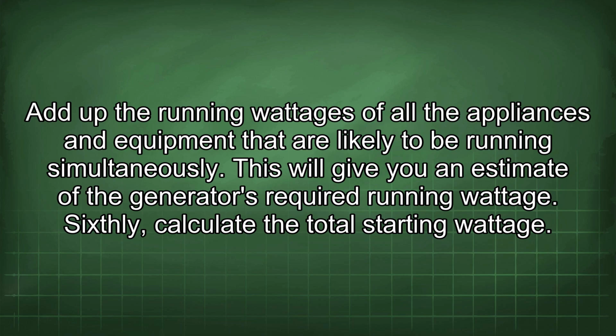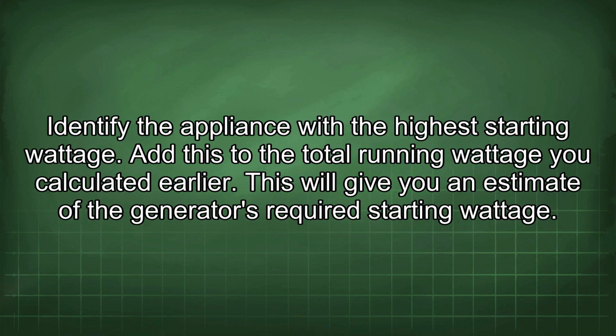Sixthly, calculate the total starting wattage. Identify the appliance with the highest starting wattage. Add this to the total running wattage you calculated earlier. This will give you an estimate of the generator's required starting wattage.